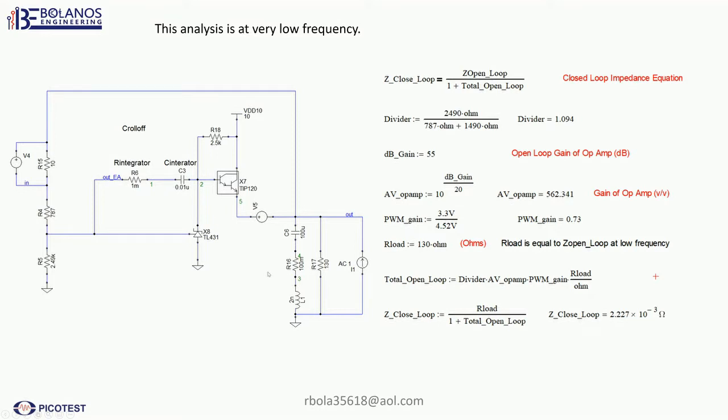And to measure the output impedance in SPICE, what you do is an AC analysis, you put a current source and set the magnitude to 1, and that current will output here. When it sees a resistor, that current will be multiplied by the resistance and develop a voltage. So the voltage at this node really represents a resistance or an impedance. Okay, so this is the way you simulate.